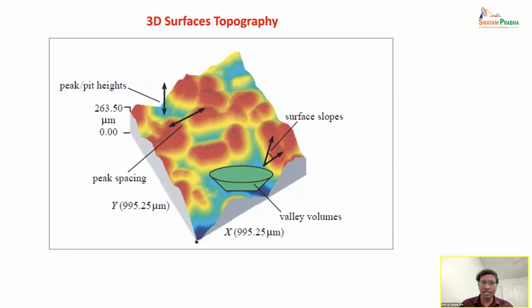So it is honing. That is how we have different characteristics of these surfaces. Now the main aim of texturing is not a random surface like this, but to give a systematic surface so that we'll be able to get the properties we are looking for. For example, if you want more lubricant to be contained in those valleys, you make dimples, like holes, and then space them in the appropriate way so that they can contain the lubricant.